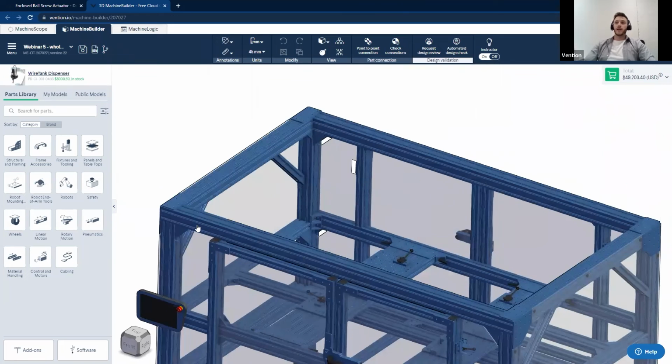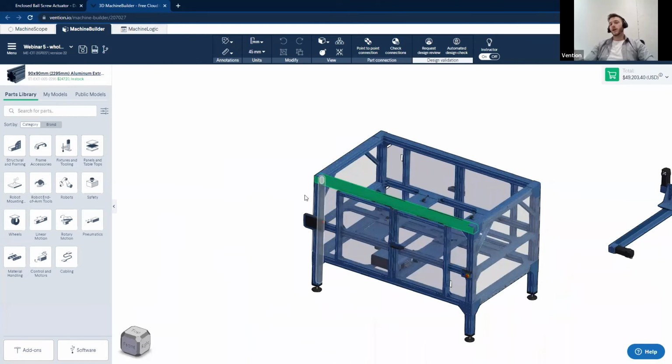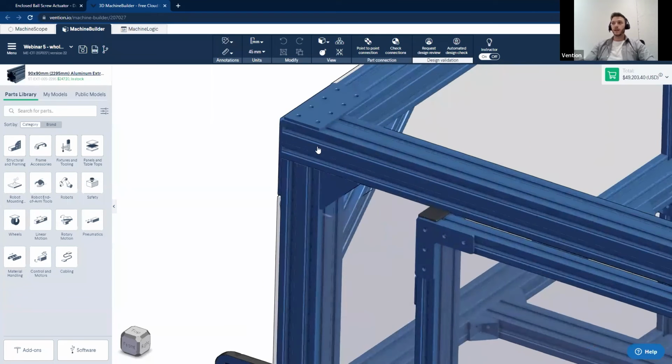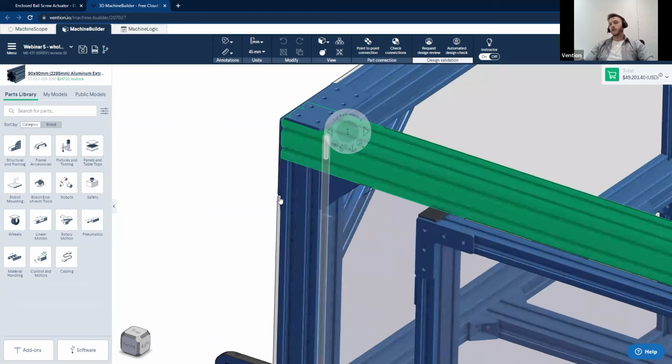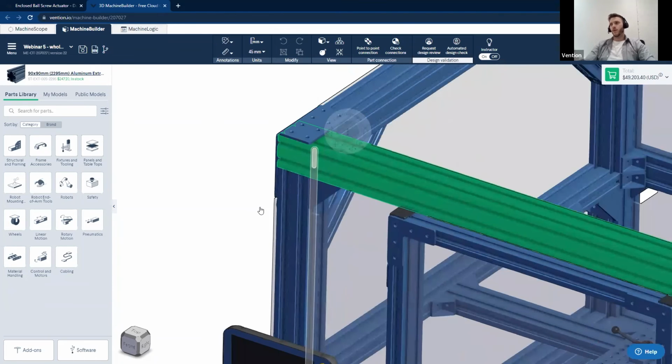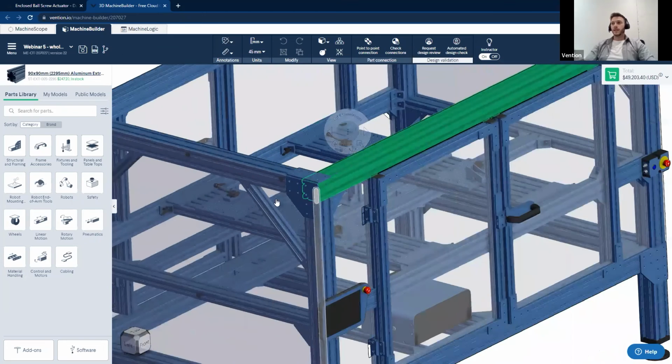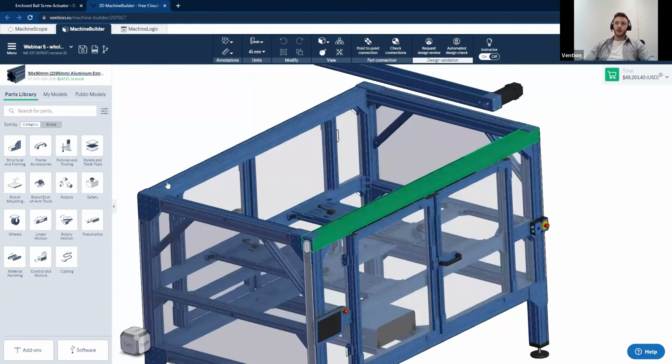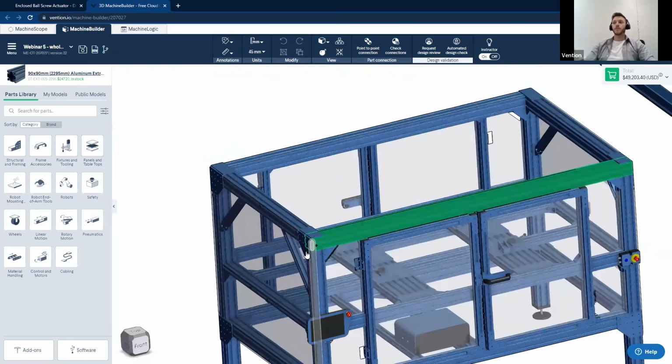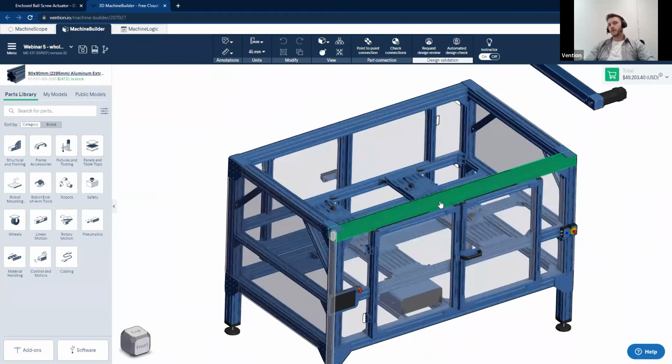The first is, if you are designing a gantry robot, to use the largest 90 by 90 millimeter profile for the skeleton or the major portion of the frame. Looking over here, we have a 90 by 90 millimeter extrusion. The reason being is it's our most rigid extrusion for designing. After this, say you have created your base frame, so you have the top, the base over here, as well as the vertical extrusions, is to mount the ones that will be supporting most of the load in compression if possible.